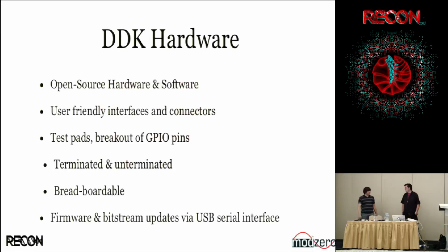I'm getting the multimeter, and I'm measuring the voltages, which is, by the way, for those who don't do electrical engineering, the first commandment of debugging electronics: thou shalt measure voltages. So we got out the multimeter, we started measuring the voltages on the test pads, and it turned out that Thorsten's USB hub was providing 3.7 volts instead of 5.